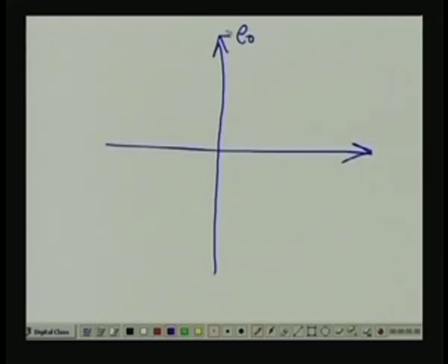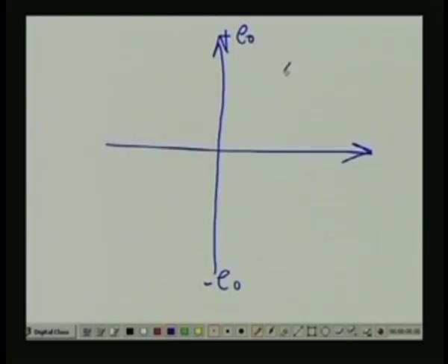Now, since it is fully rectified, it is DC, even though our excitation voltage is AC. Our output is now DC, because the two secondaries are fully rectified and we are adding them algebraically. So, the output voltage will look like this one.